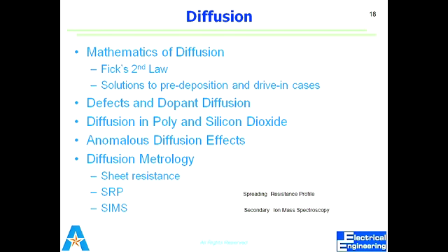I believe you know about resistivity at least. Do you know about resistivity? Yes, it is defined by rho. This parameter is known. Then sheet resistance Rs is always equal to resistivity divided by the thickness of the thin film. So if you know the resistivity and you divide it by the thickness of that thin film we are talking about, you can calculate the sheet resistance.